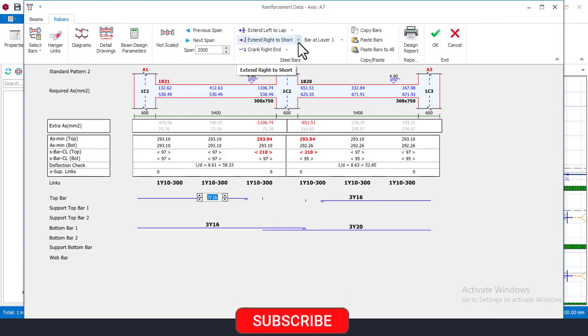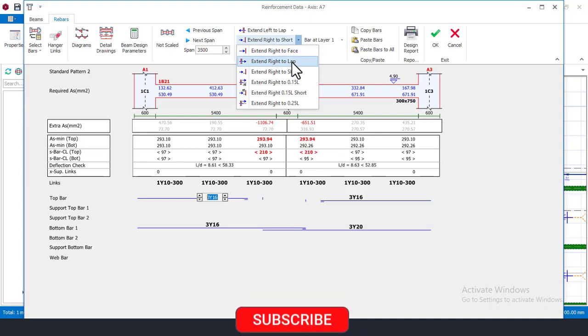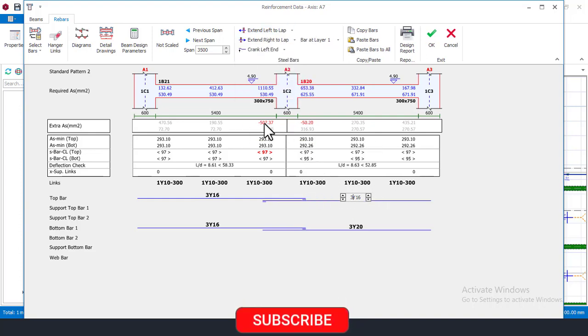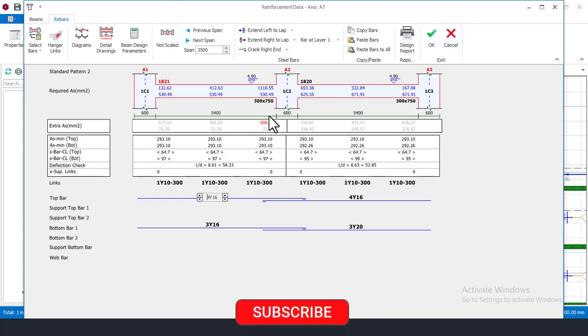So I'll come here right now, click on this and then say extend right to lap. Okay, and also come here again right now and extend left to lap. Okay, so always use lap. Okay, and I'll now come here right now. It is still failing at the top here. You can see that this extra area of steel here is still failing, as you can see that. So I'll come here and make it to be 4Y16 and come here again to be 4Y16. At that, it is still failing right now.